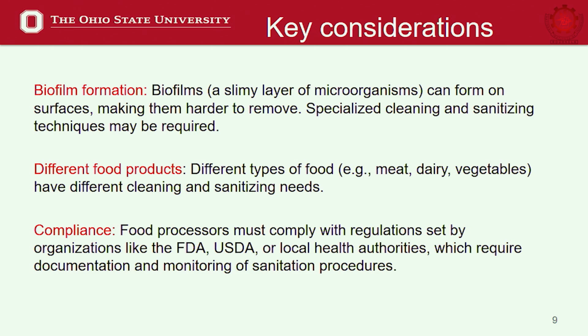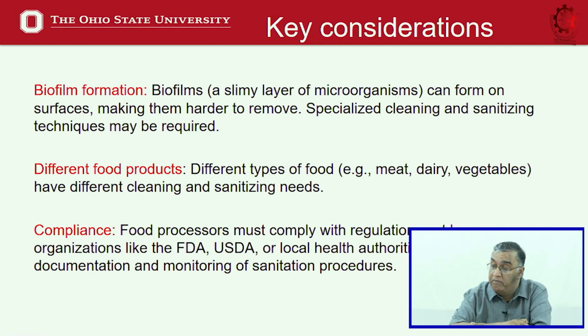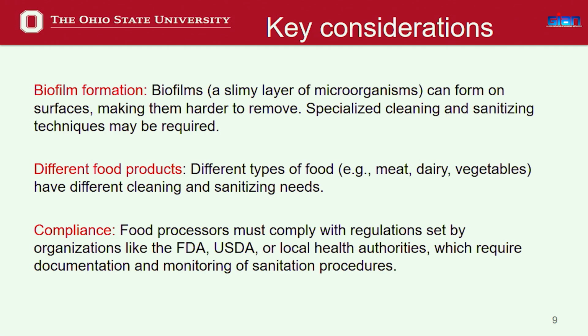Yesterday, we talked about biofilms. Biofilms can form on the surface. Basically, it's a small thin layer of microorganisms, and they are much more difficult to remove compared to even some of the foulant type, because microorganisms are going to deposit in multiple layers, and then they form a colony, and then they are much more active, and it requires much greater effort. So, you need to have a specialized cleaning and sanitation technique.